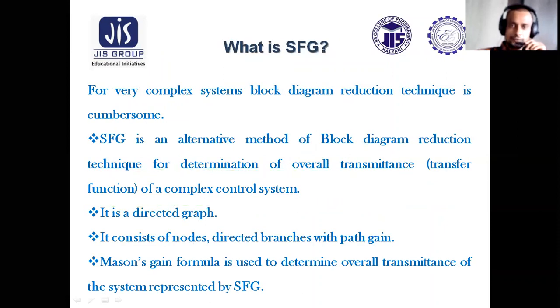What is SFG? First we'll discuss what a signal flow graph is, or why we should study signal flow graphs. The purpose of studying signal flow graphs is the same as that of block diagram reduction technique. That means block diagram reduction technique and signal flow graphs are both used to determine the overall transfer function of a system. But block diagram reduction technique sometimes is difficult to apply for a very complex system.